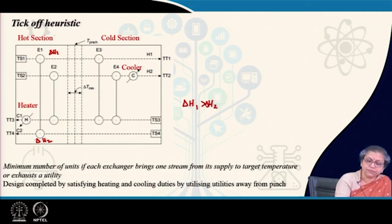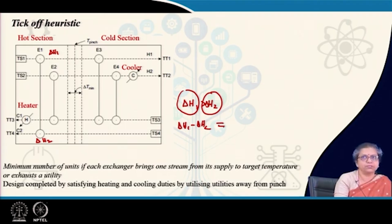By this exchange the entire delta H2 heat can be removed, and after that there will be some amount of delta H1 minus delta H2 heat left in stream 1, which has to be removed either by exchange with some other cold stream or by a process utility.